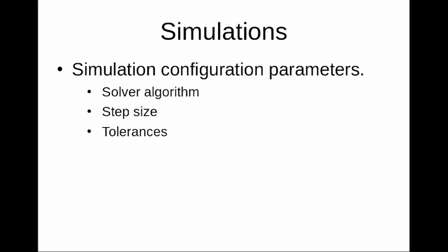Basically, most of the power electronic systems belong to a special category known as stiff systems. These are systems which have multiple time constants which are far apart. Like in a motor drive, for example, the smallest time period involved may be the switching time of the switches, and the largest may be the electromechanical time constant of the motor. Such systems require particular care while simulating.